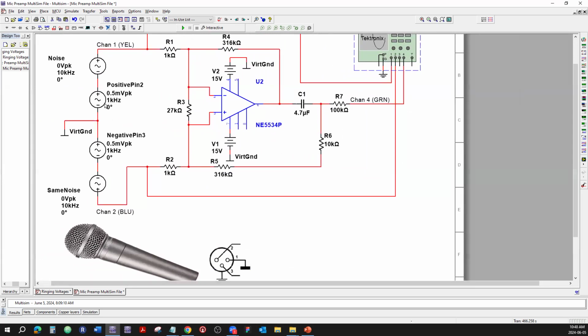They are the same frequency, same voltage, 180 degrees apart. Right now it's 0 volts, because first I'm going to show you without the noise what the signal looks like. They're ready to make noise, but these will be in phase, because the noise will be in phase. Whatever is in phase that gets into here is being ignored. Whatever gets out of phase is being interpreted as a signal.